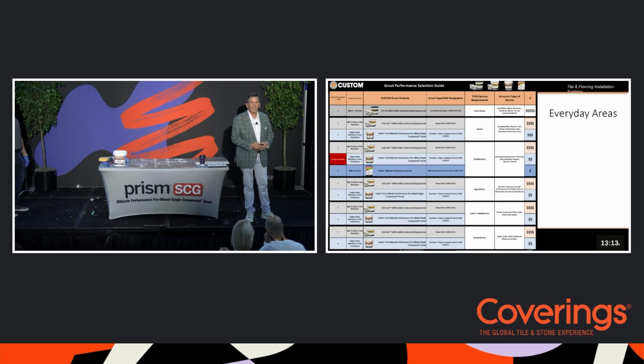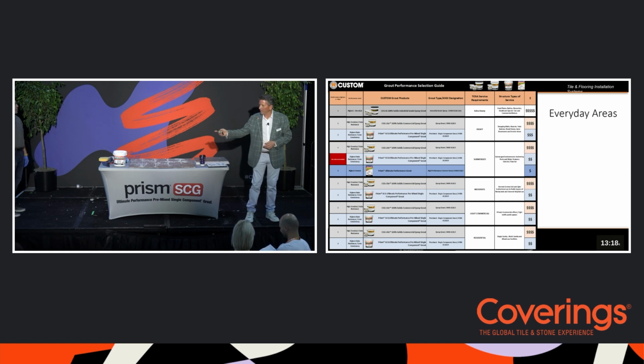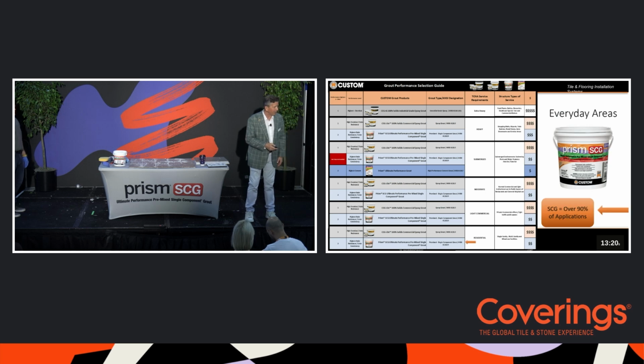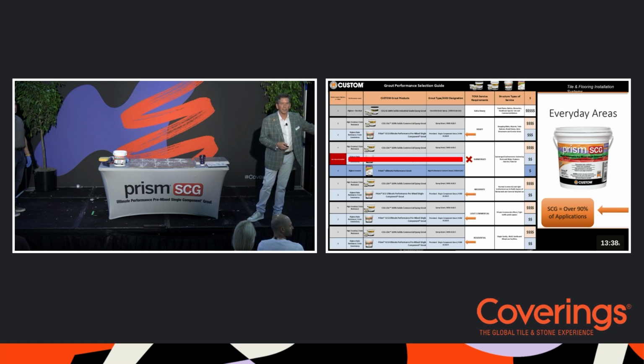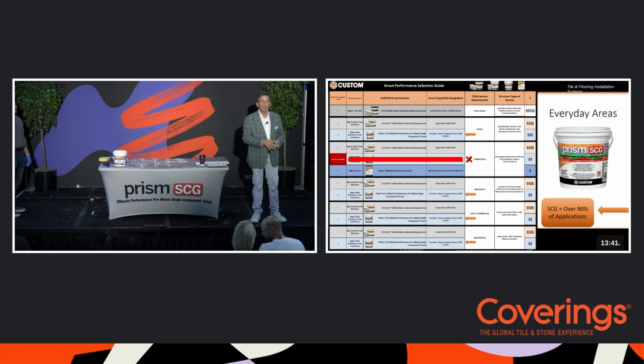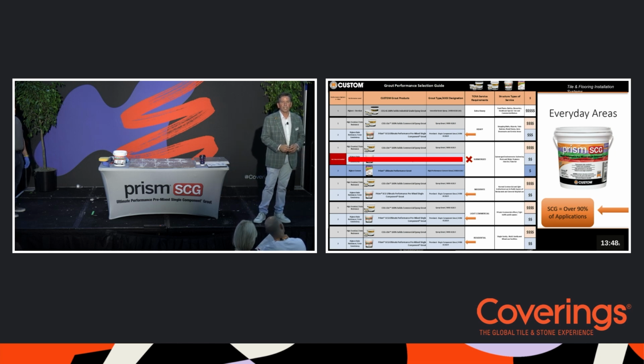So where can the new second generation Prism SCG, single component grout, be used? Well, we know it can be used in residential. We also know it can be used in light to moderate commercial, but we also know it can be used in heavy applications. Where we don't recommend the second generation materials is in submerged applications. We will get that in the third generation. That's the evolution of the category. We haven't found a ceiling yet. We will continue down that road. The next generation will get submerged.